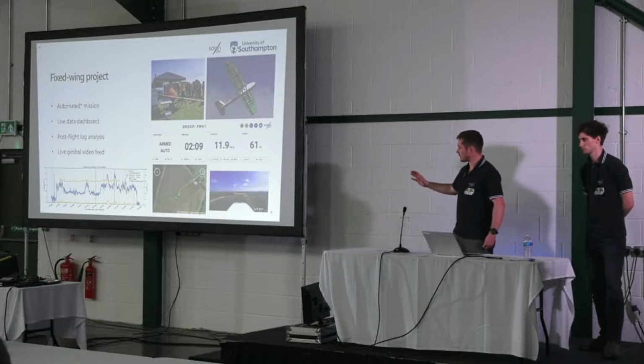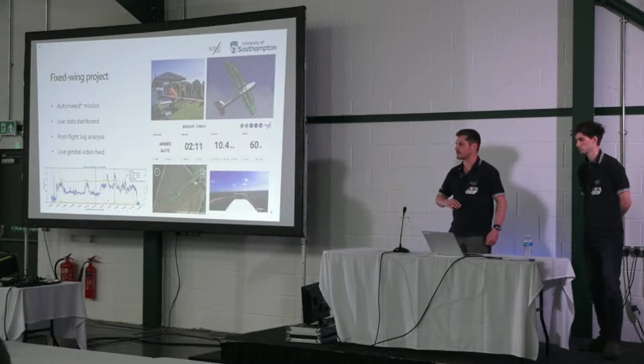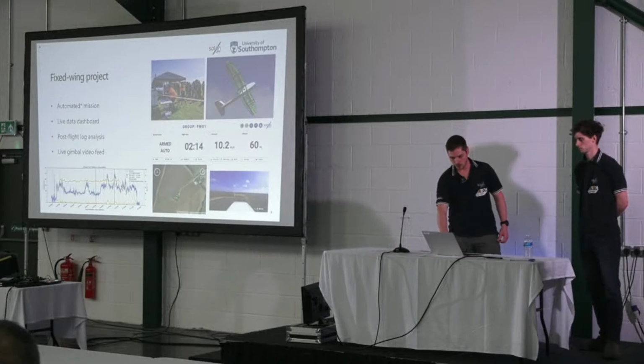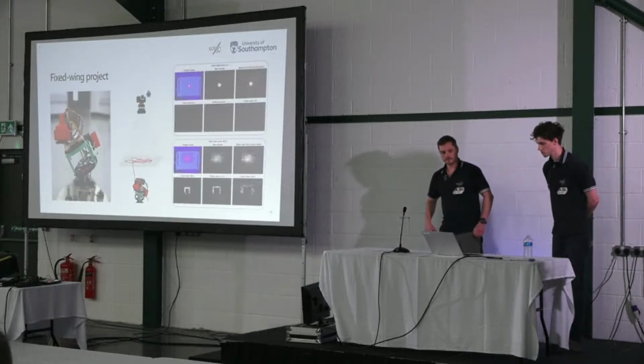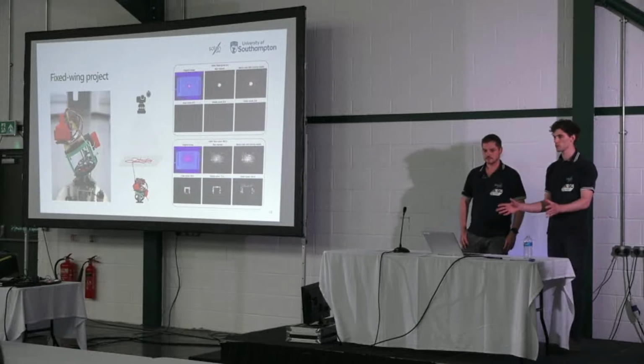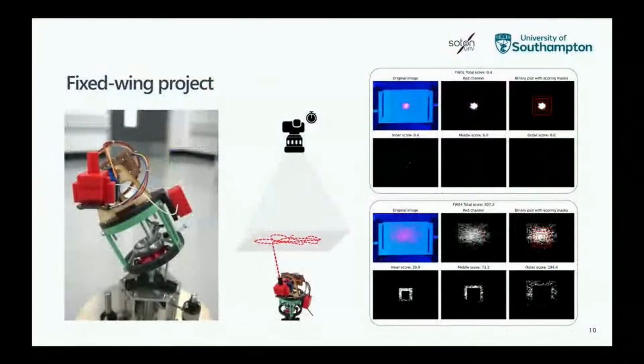But to test the gimbal, we actually do some testing inside in the lab, and Cameron's going to talk briefly about that. Yeah, so here we have one of the gimbals on a custom tilt table that we've made. It's basically just a swash plate that's upside down. We can use this to put in roll and pitch perturbations. We can also apply vibration to it by shaking the stepper motor very quickly.